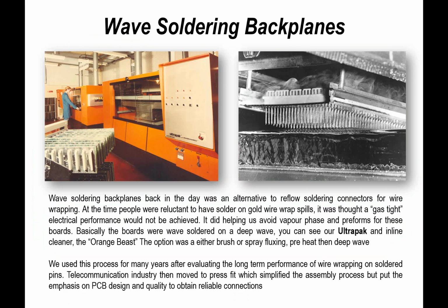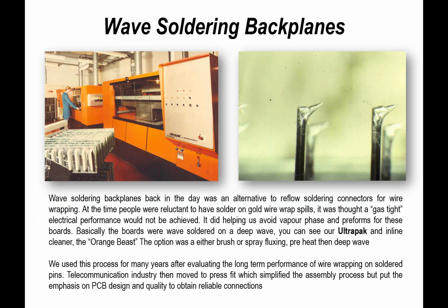Those were made up into much larger frames during the assembly process. And again, you can see a historical, this is not me only having a black and white camera at the time, the pins coming out of the wave. This was part of our evaluation trials. The disadvantage of this process is you've got to maintain your wave solder machine pretty much on spec, and also